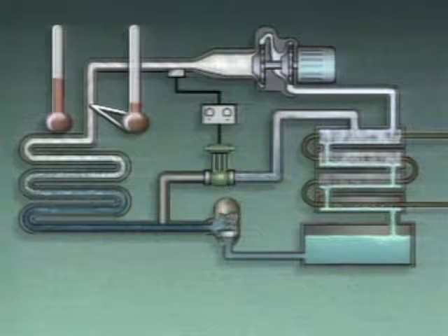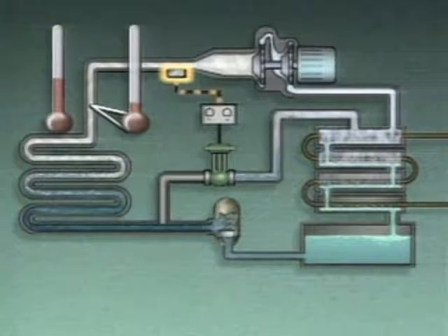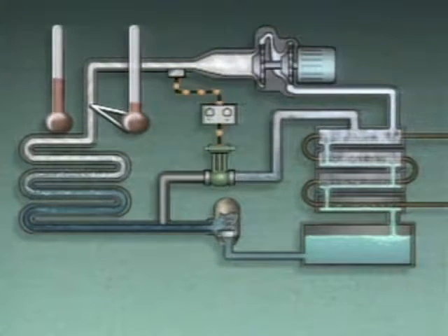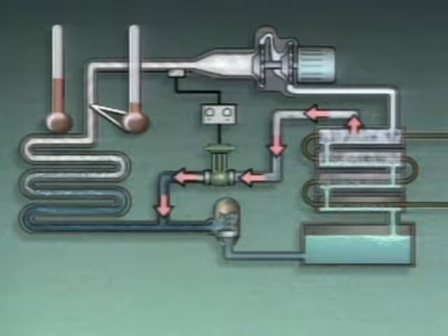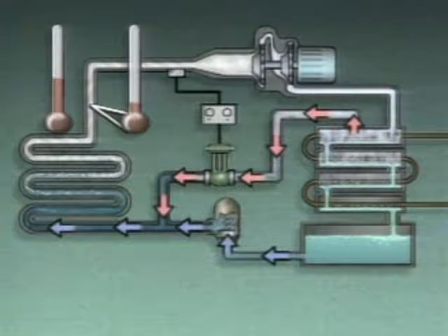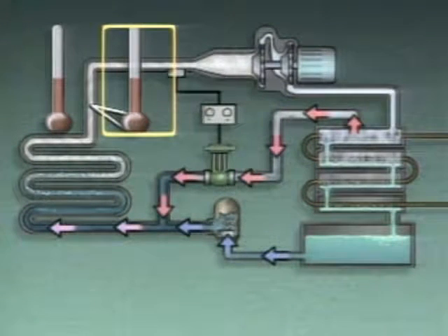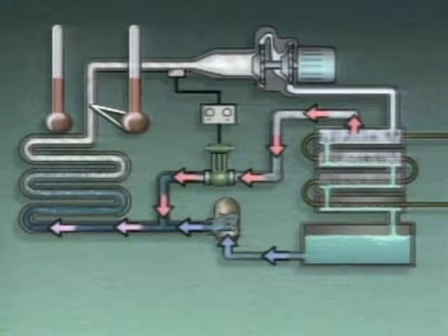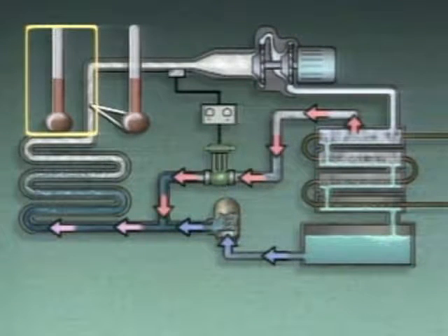When the temperature of the refrigerant flowing to the compressor drops, a temperature sensor sends a signal to a controller, which in turn sends a signal to the bypass line control valve, causing it to open slightly. This allows some of the refrigerant from the discharge of the compressor to be routed to the evaporator. This warmer refrigerant mixes with the refrigerant leaving the expansion valve and increases its temperature. As a result, less heat is removed from the substance being cooled, and its temperature increases back to the desired value.